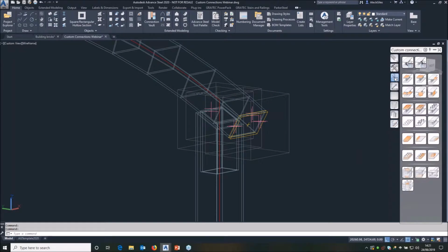So again, I'm going to go to the building bricks page and choose plates on a beam, bolts on a beam, not bolts on a plate. It's going to be on this beam. I need to make sure I choose the smaller beam because the positioning will be based on the position of that beam, not on the length of the overall column. So that's the positioning I want, and I'll choose the bottom because again that's the end I need to reference for the positioning. Do I want to select connecting objects?